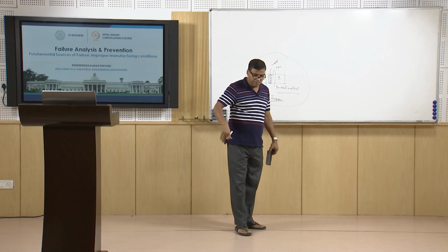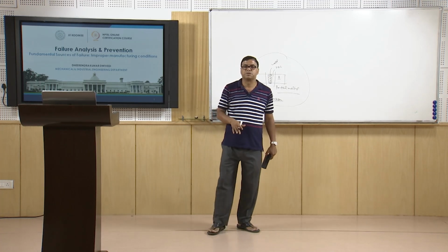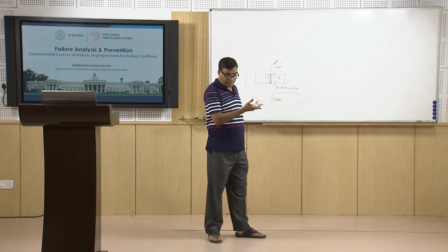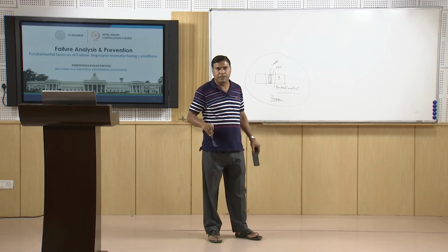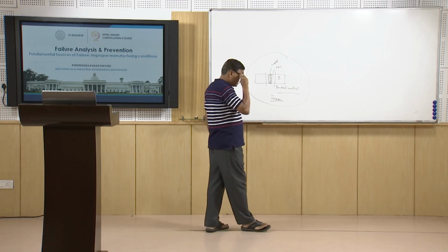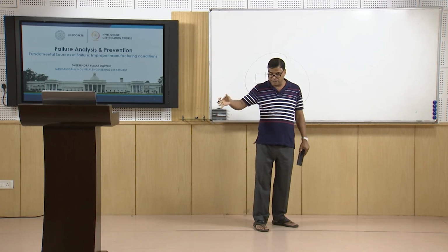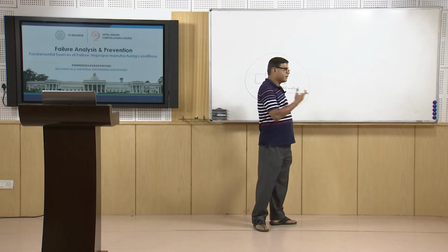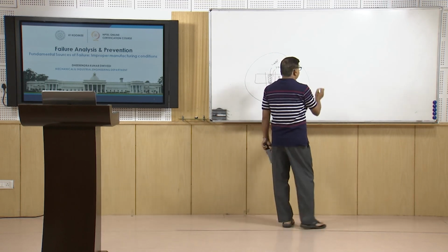So, that is another category of process. If the process parameters like the rotational speed, the forces being applied, and the design of the tool being used are not appropriate, then it can lead to a number of discontinuities in the weld nugget, which can act as a source of weakness. So, sometimes despite having good metallurgical continuity, the joint may be weaker or stronger, and accordingly we need to see where the joint will fail.